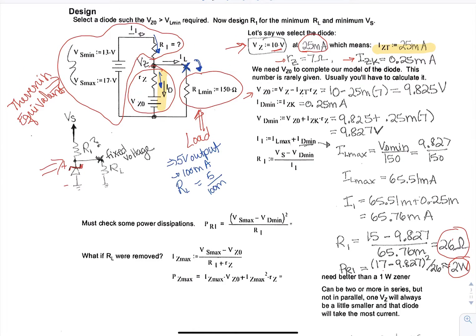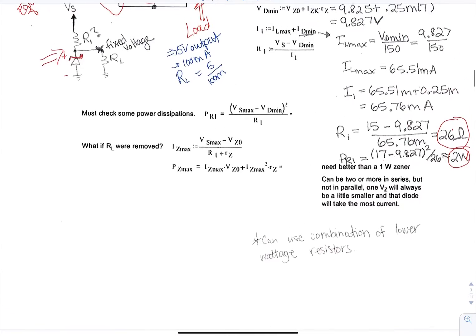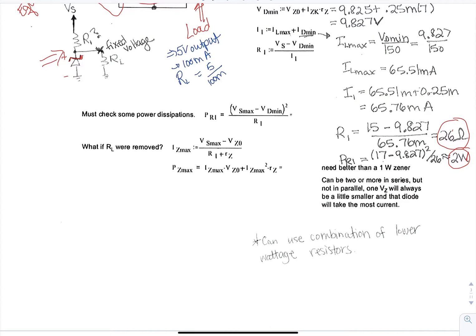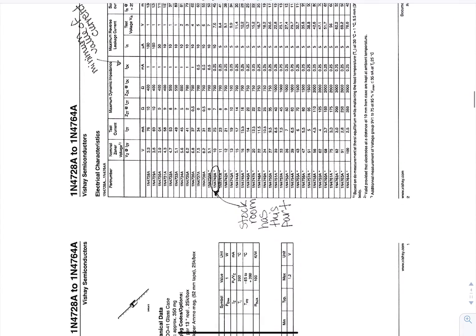The resistors that you've seen so far have only been 1/4 watt rated resistors. So make sure you get the higher rated resistors, so that it will match the power rating you're expecting from this if you build these.